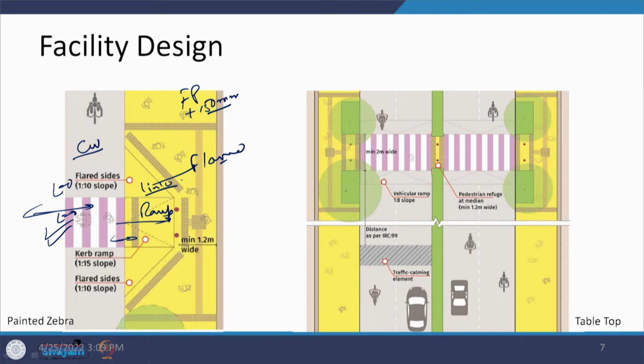Along with these things, what you can see is that the tactile tiles or the warning tiles are also being provided. So, we have the things here which define that you are approaching something beyond this and should be careful about it. And then it allows the person who has nothing to do with the crossing to cross along. So, that is another category of tiles. There is a sort of direction tiles which are taking the person straight. But at the location where the crossing is there, again the warning has been issued to the person who is differently abled, that at this location there is something, some junction is there.